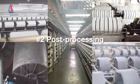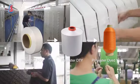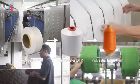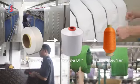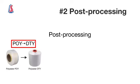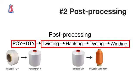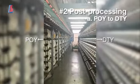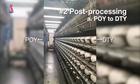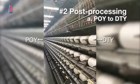Number 2. Post-processing. The post-processing of chemical fiber refers to the processing that can make the spun nascent fibers suitable for textile production. Post-processing can be roughly divided into the following 5 steps: POY to DTY, twisting, hanking, dyeing, and winding. I will explain every step to you. POY to DTY, combining the drawing and twisting process on the same machine. The produced yarn is called draw texturing yarn.